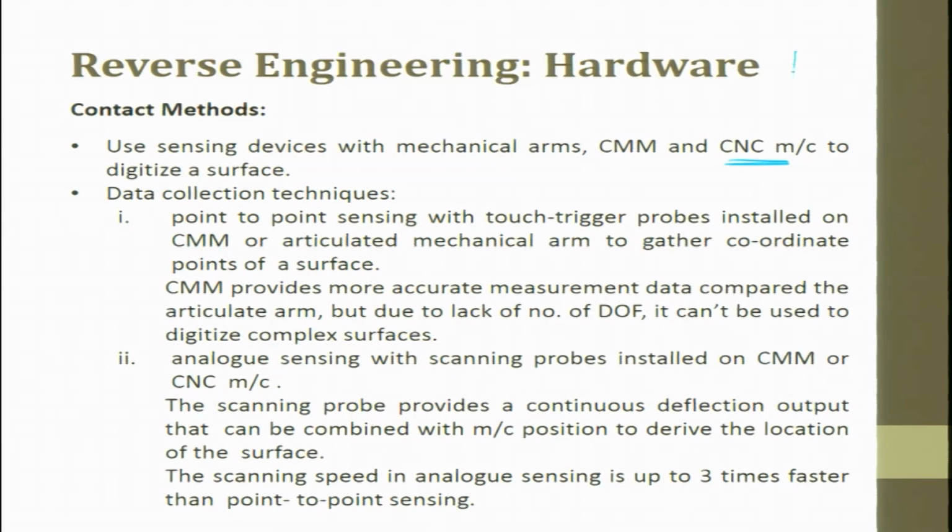What you do is, you take steel or a metal, and you have a workpiece as metal. So you make a connection between these two, and when it comes closer, when it touches, the resistance goes to infinity, and from there you can start noting down the XYZ data points. So this fellow can move step by step in the XYZ plane. So a CNC machine can be used as a coordinate measuring machine.